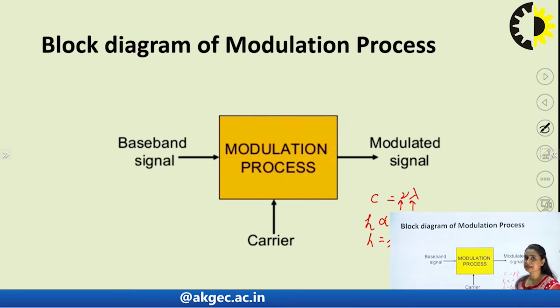So we can see from here, if my frequency is low, then lambda would be too high, right? Because the multiplication is a constant. If this is low, this has to be high. When this is high, the height of the antenna will also be high. So let's take the example of a 10 kilohertz frequency.